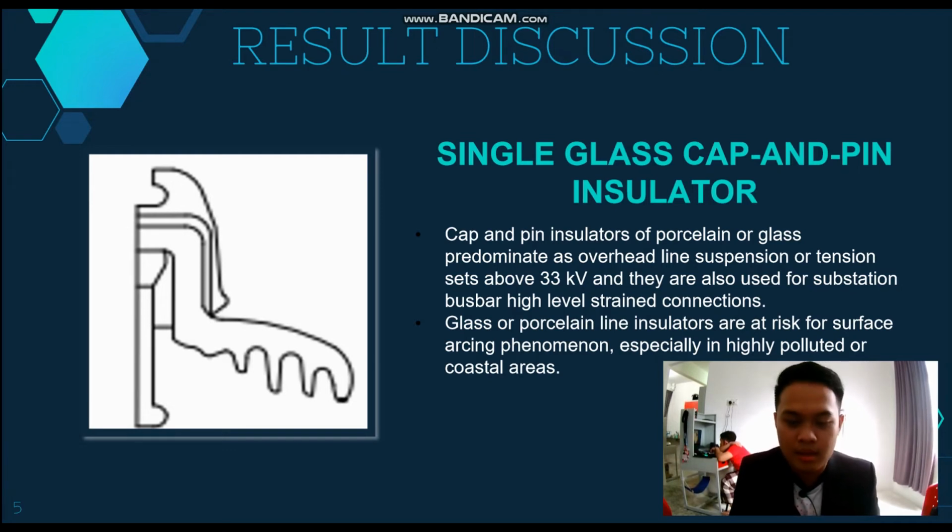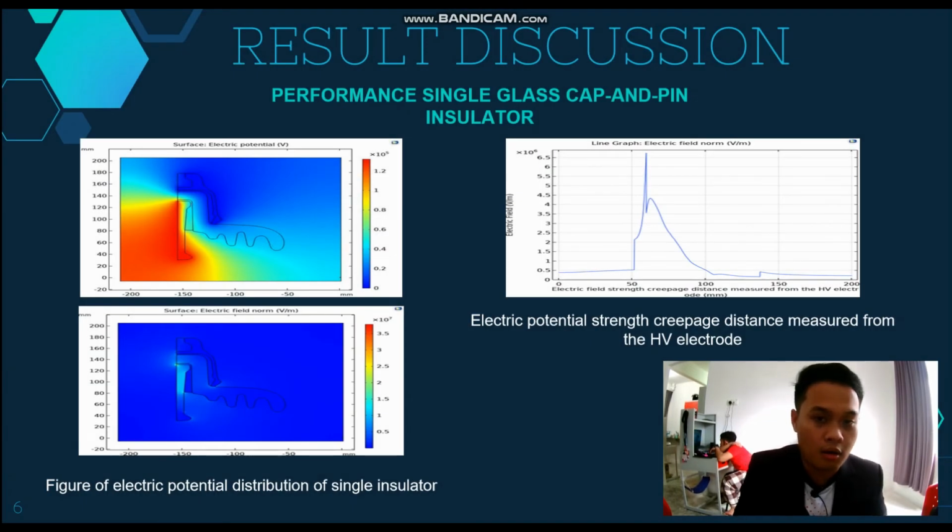connections. Next, due to its type of material, which is glass or porcelain, the line insulators are at risk of surface arcing phenomenon, especially in highly polluted or coastal areas. So this is the performance of the single glass cap and pin insulator.